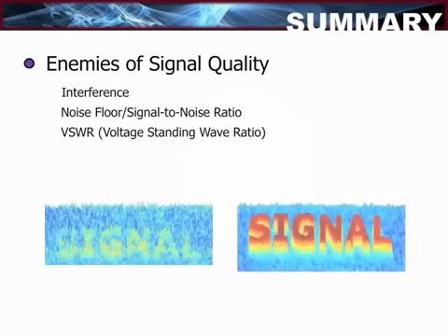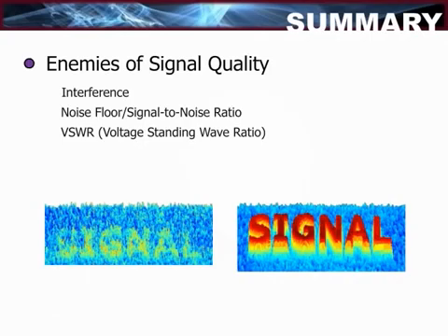The noise floor in an RF environment can be compared to the ambient noise in a real-life situation, such as being at a crowded restaurant or standing near a waterfall. The signal-to-noise ratio is the power of the received signal over the noise floor. If the noise floor is too high, the signal will not be able to be interpreted. This would compare to being at a jam-packed sports arena with a person sitting next to you whispering. Most likely, you would not be able to interpret the whispering.